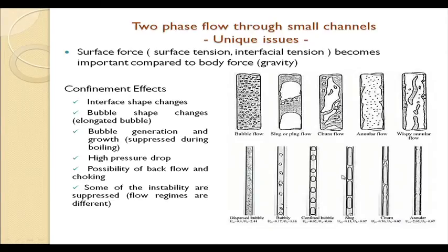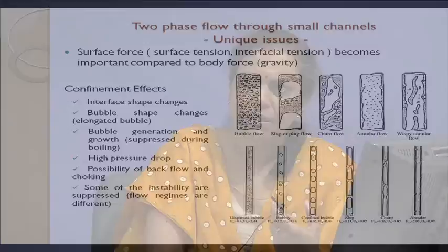As the Taylor bubbles start becoming larger and larger, they come into each other's wakes and start coalescing with one another. There is a portion where they are coalescing, yet there can be some liquid bridges. They are so short that we cannot call them liquid slugs.